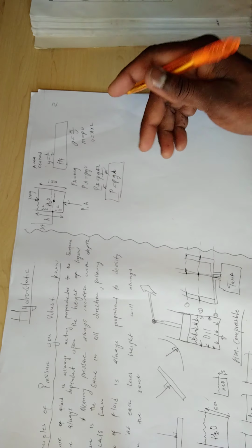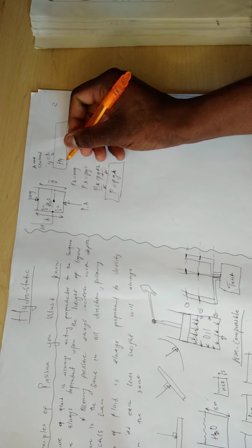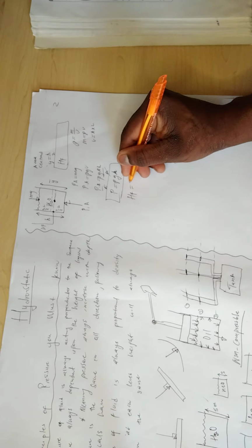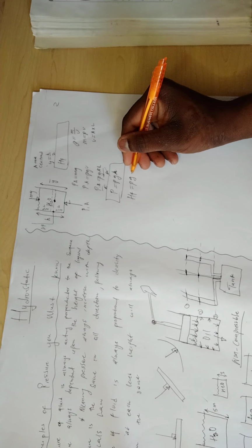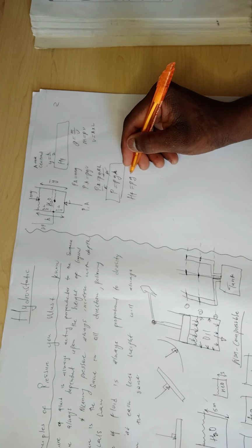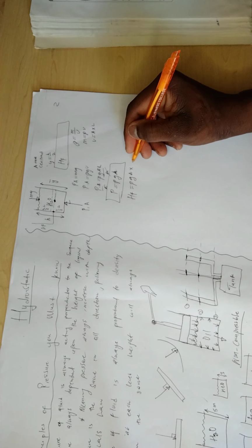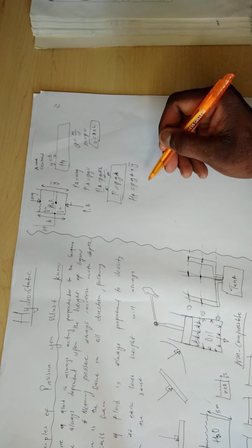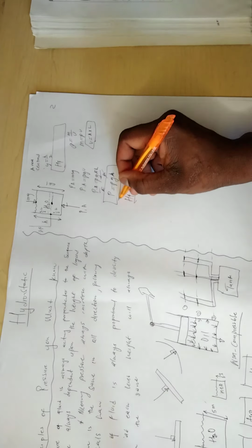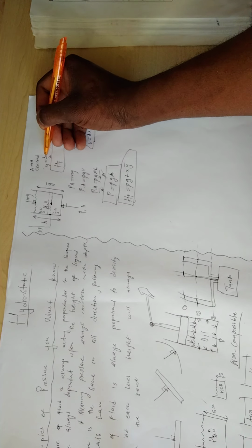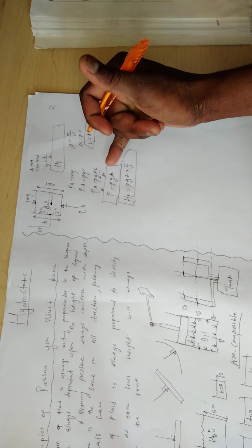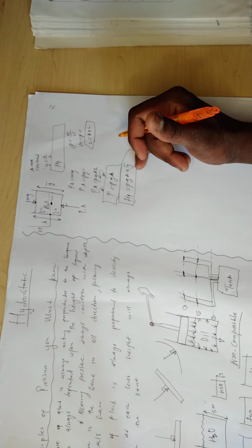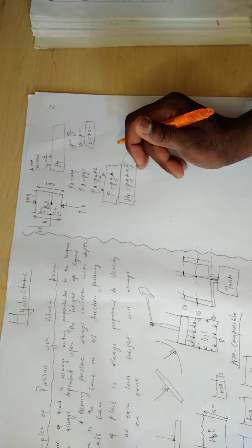And we're going to use this formula to find a pressure. But when we are looking for the hydrostatic force, we're going to say hydrostatic force equals density, gravity, area multiplied by y bar. It means we're coming back to the volume. This part here is a volume. So our y bar, we calculated it here, which is height divided by 2. So this is how you're going to get your pressure, and this is how you're going to get your hydrostatic force.